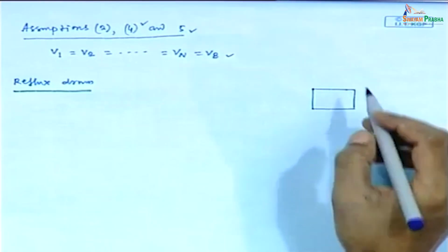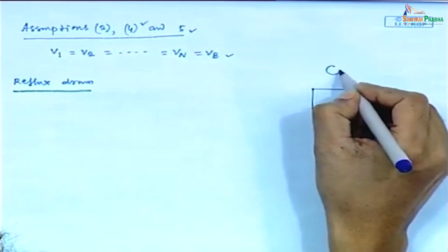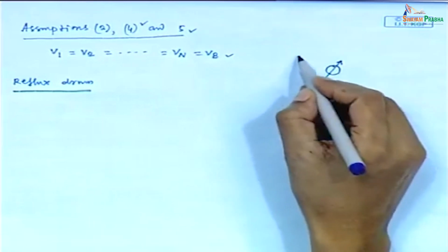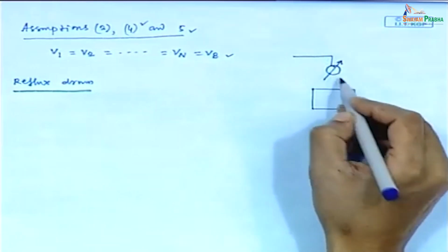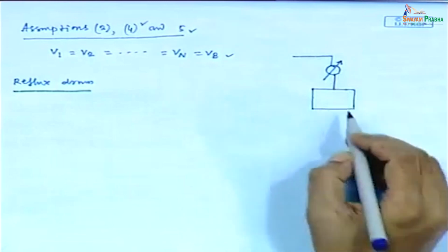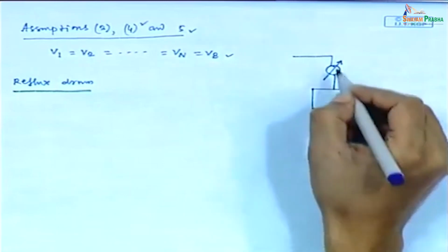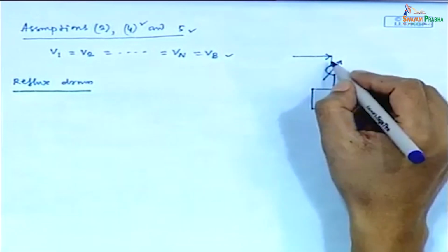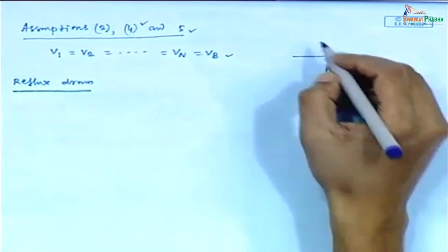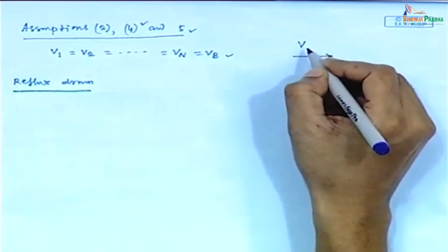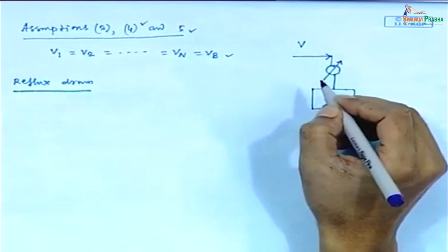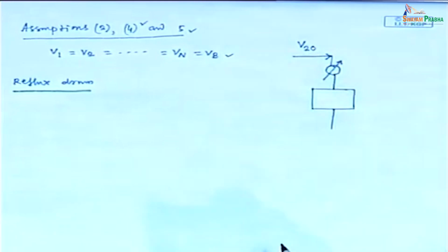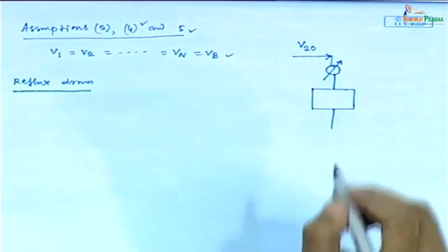Since we have considered there are no dynamics of the condenser, we can include it here without developing any modeling equation for it. The vapor stream entering the condenser, we represented previously by Vn. N is basically 20, because we have considered a total of 20 stages.